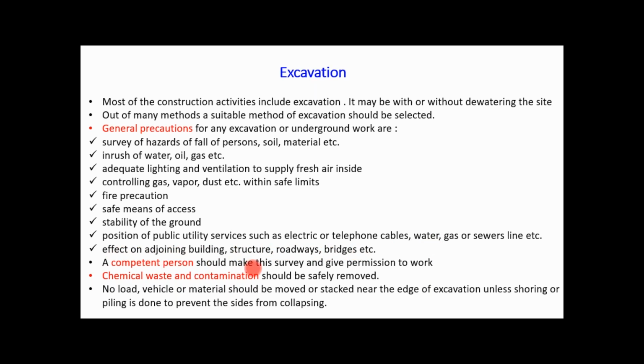A competent person should make this survey and give permission to the work. Chemical waste and contamination should be safely removed. So no load, vehicle or material should be moved or stacked near the edge of excavation unless shoring or piling is done to prevent the sides from collapsing. So we have to take care about all these